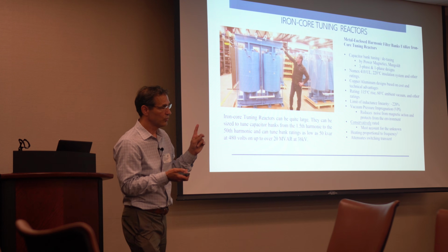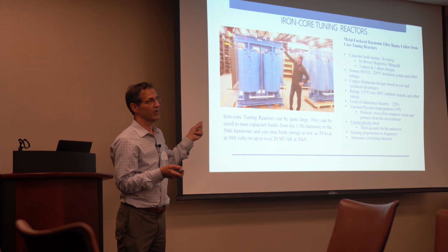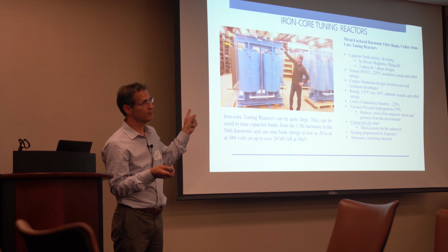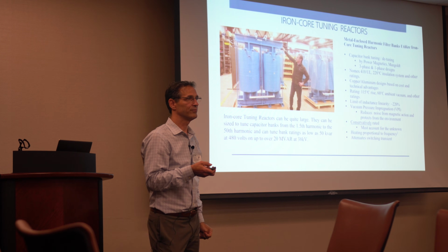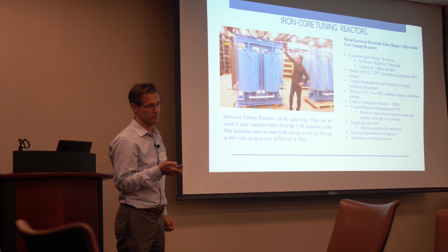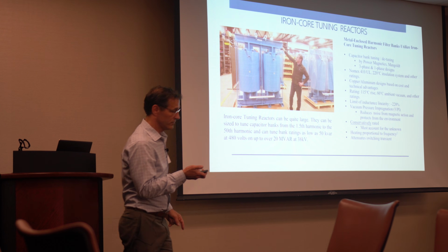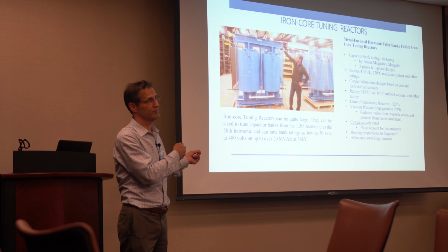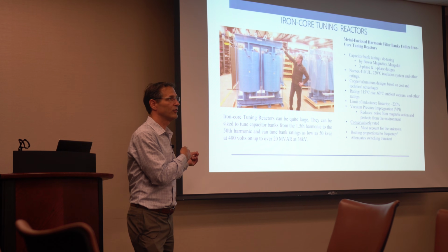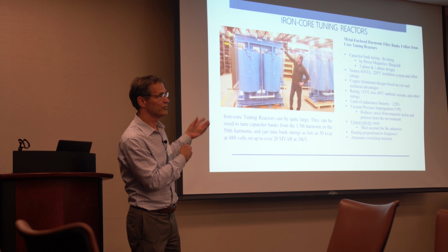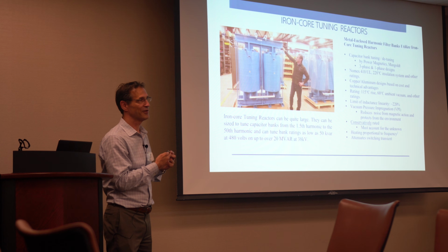So the number one problem with harmonic filters is underspecified reactors, whether it's air core or iron core, underspecified. In other words, underrated. Somebody did not put enough rating in the design, and you're not paying much for that extra rating. So for us, if you add reactor rating, we sleep at night. I don't have to deal with phone calls on Saturday saying I'm tripping on thermal overload, or the thing is loud, or it's failed, or there's stuff dripping out from underneath.